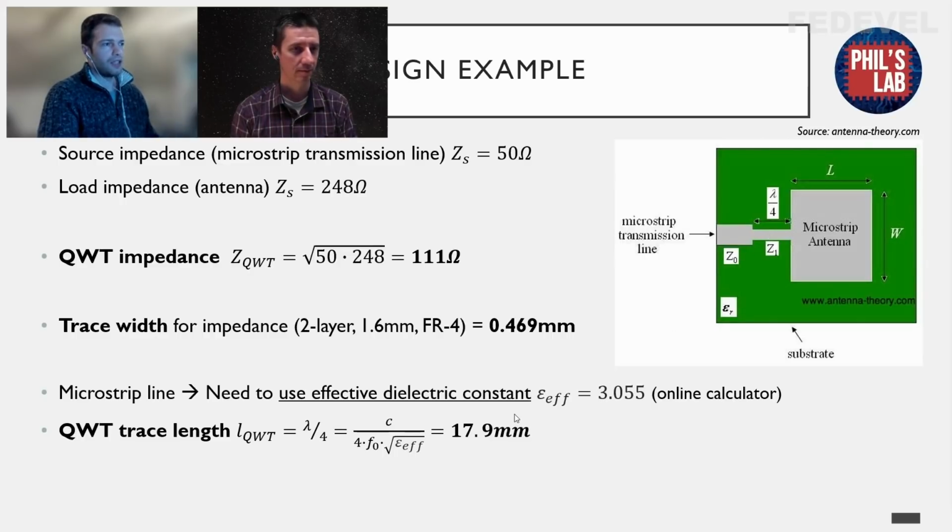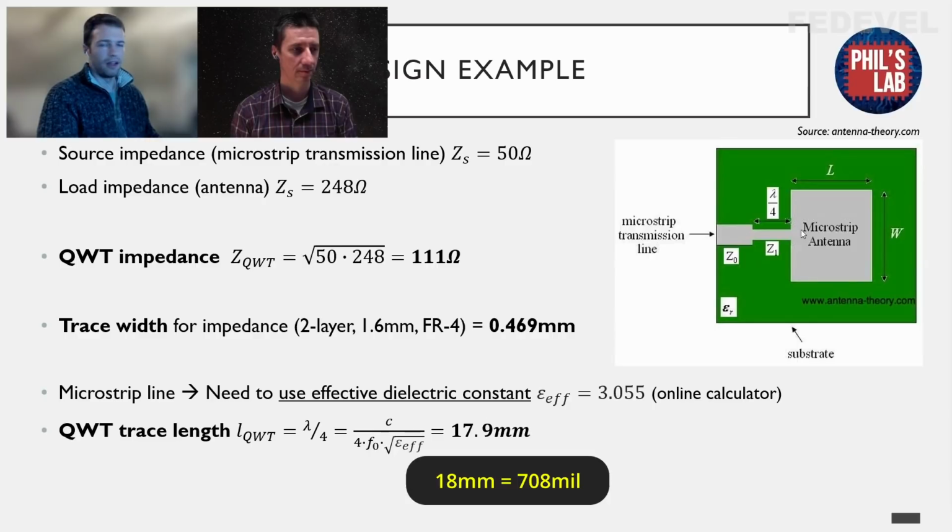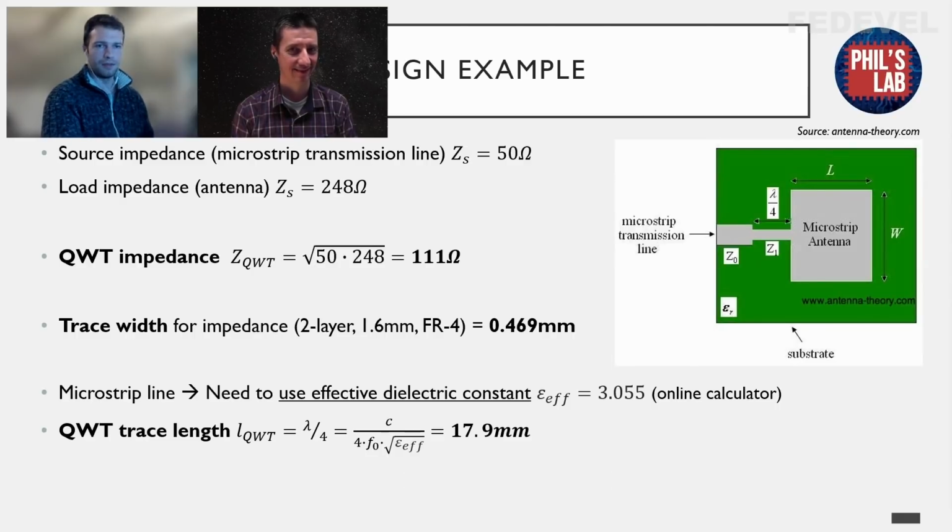So that turns out it needs about 18 millimeters of length. So 2 centimeters, that's quite considerable to add to a PCB again. So that's why this design, even at 2.4 gigahertz, which seems like a fairly high frequency, at least for fairly common designs, is quite considerable.